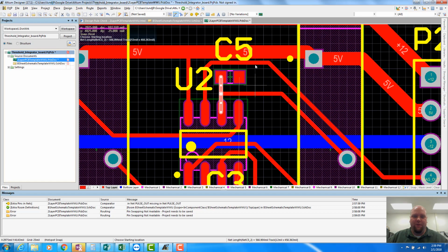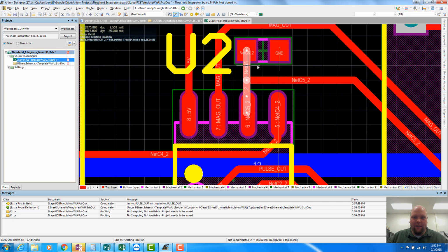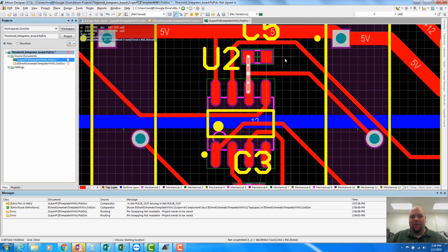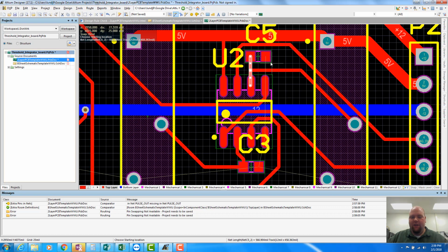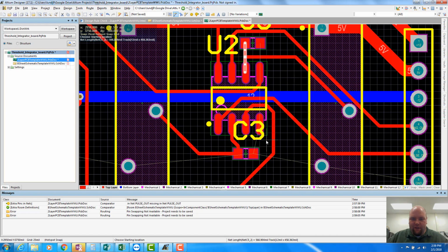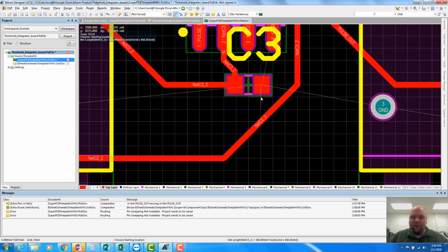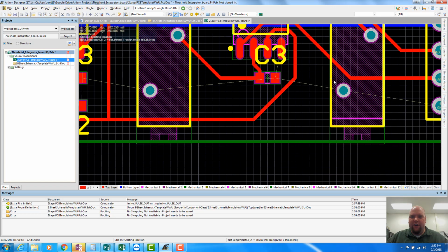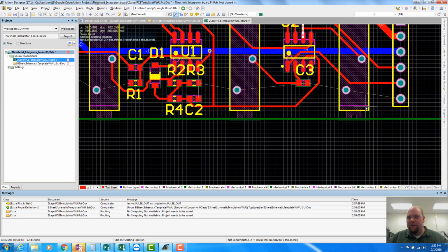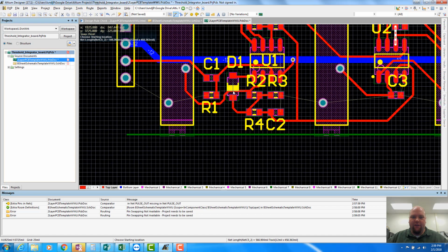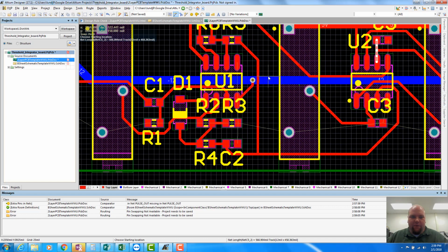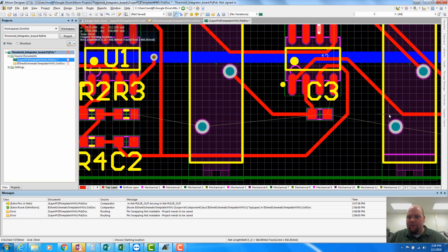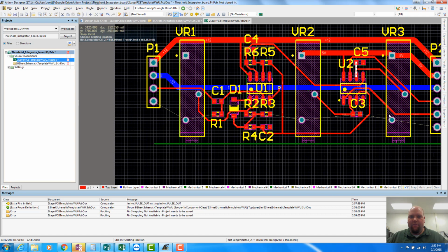So we've created a condition where I'm guessing this guy's going to be tough to get a ground signal to. That's alright, we can plop down a via there. All ground, all ground, all ground, okay. So I think we got everything routed now, with the exception of our ground connection. And we did a pretty good job of keeping it up on the top layer. That's not bad.